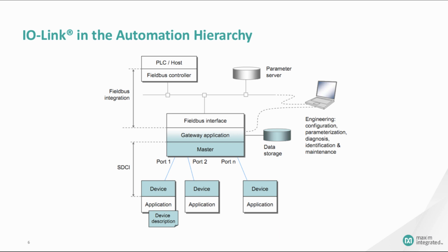IO-Link functionality in a system reduces maintenance and increases uptime. The devices can be plug and play with parameter settings that can be downloaded from the controller. Customers no longer need a technician on the floor to do this. Machine downtime is no longer needed to reconfigure the devices. IO-Link allows for continuous diagnostics and improved data logging and error detection. And it's also an easy standardized installation with commonly used connectors and cable that allows direct binary sensor upgrades. IO-Link sensors now have configurable settings for the PNP, NPN, or push-pull that can be changed on the fly.